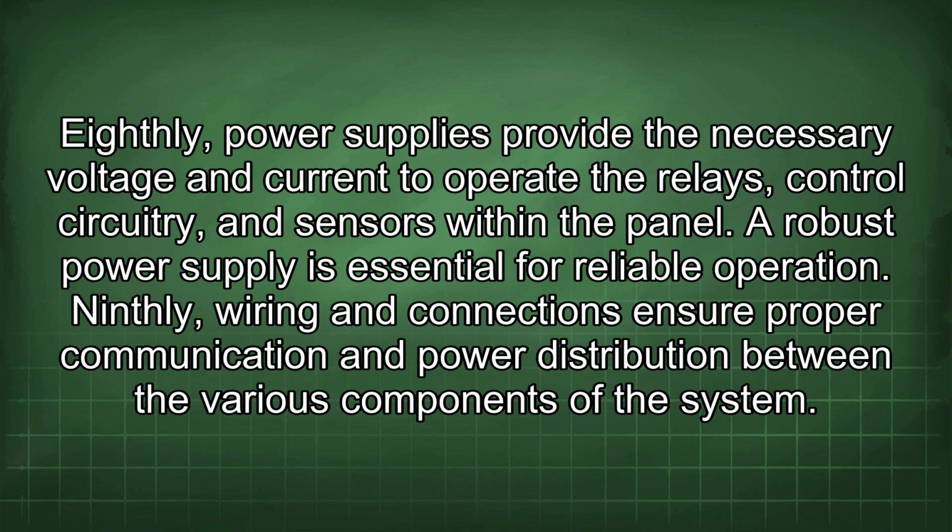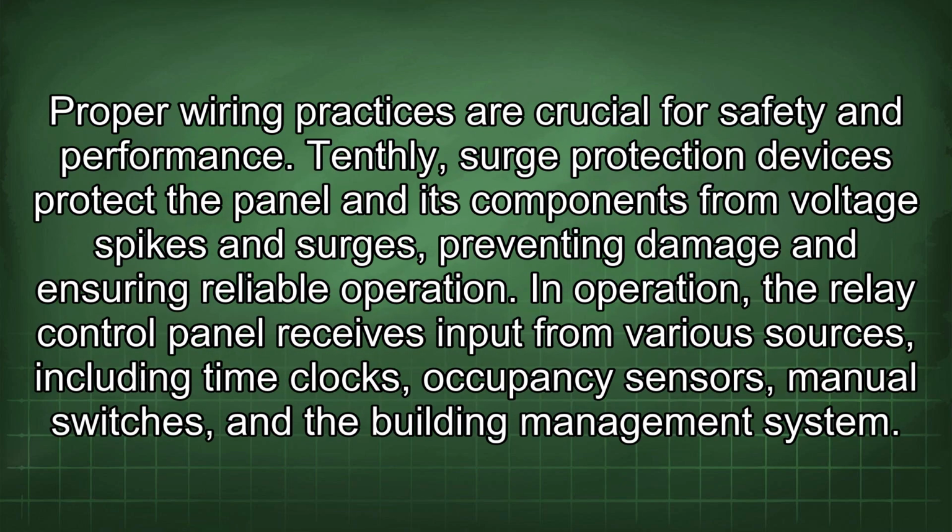Ninthly, wiring and connections ensure proper communication and power distribution between the various components of the system. Proper wiring practices are crucial for safety and performance. Tenthly, surge protection devices protect the panel and its components from voltage spikes and surges, preventing damage and ensuring reliable operation. In operation, the relay control panel receives input from various sources, including time clocks, occupancy sensors, manual switches, and